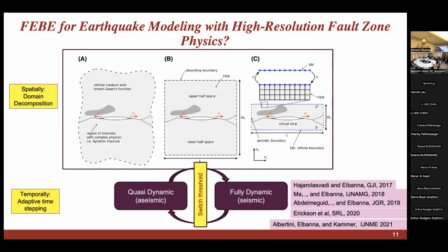And the fault is always located on the boundary between the elements here. In this approach and in this talk today, yes, but we do have techniques that allow the fault to evolve naturally. For example, with phase field, we co-developed a methodology where we can use phase field consistent with rate-and-state friction and then allow the faults to propagate anywhere, because these phase fields are diffusive and hence can be discretized as bulk entities. Excellent question.